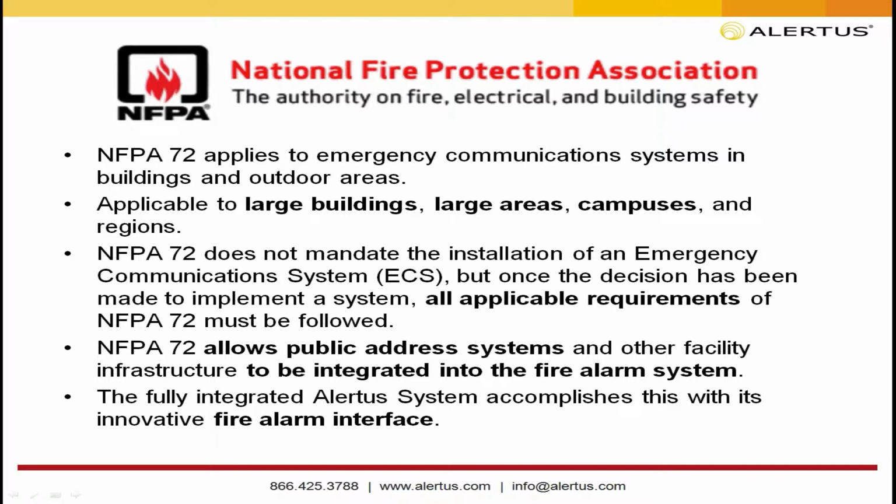And what we want to do here is make sure that everyone understands that at this time, mass notifications are not required by this code. However, whenever a customer of yours or yourself, as being the lead, is thinking about getting a mass notification system installed in your facility, then the code actually takes effect, because it dictates that whenever somebody wants a mass notification system installed, Chapter 24 of NFPA 72 is required to be followed.